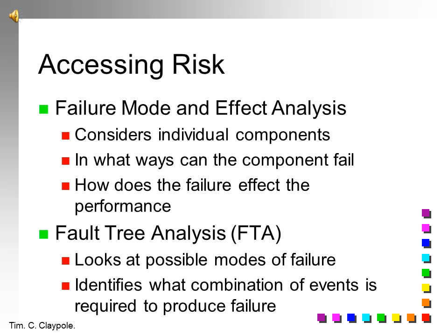Fault tree analysis looks at it from the other end. It looks at the possible ways in which a device can fail, and then it identifies what combinations of events are required to produce a failure. If you can put a statistical value to each of these events, you can then combine them to make an estimate of how reliable your design is going to be.